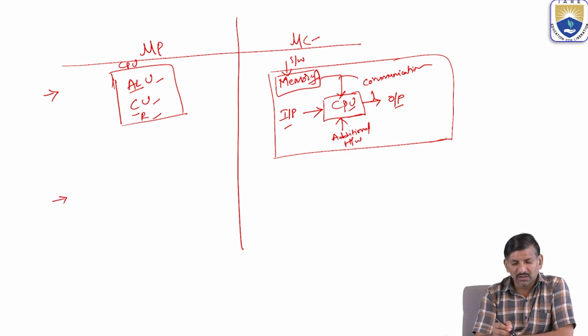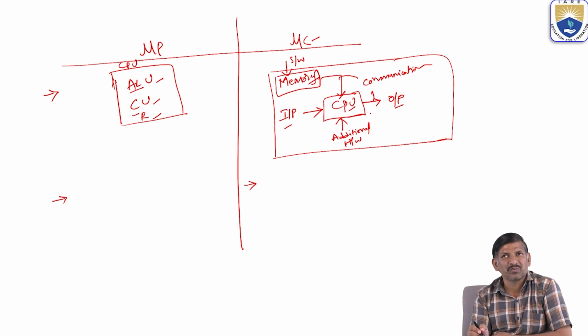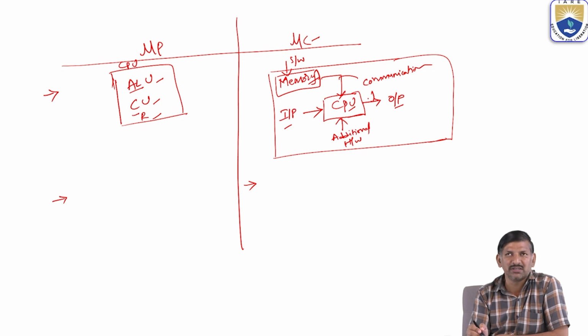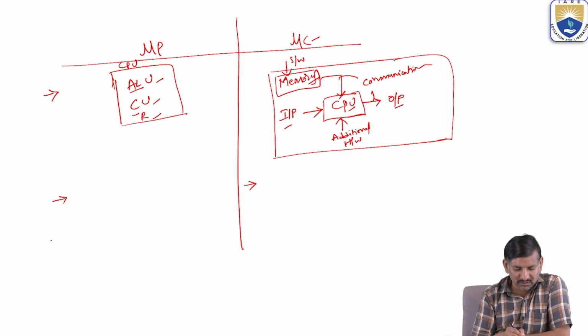Second, microprocessor based embedded system design requires external components like external memory, external IO peripherals, external hardware, and external communication peripherals. Whereas in microcontroller based design, mostly everything is within the chip. If it is not sufficient, only then can we go for external components. Mostly all these are available within the chip, so there is no need to purchase external components.